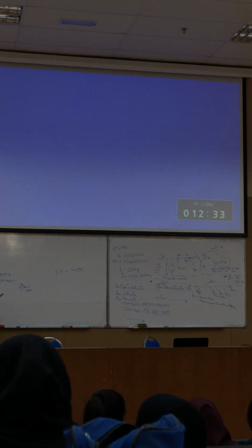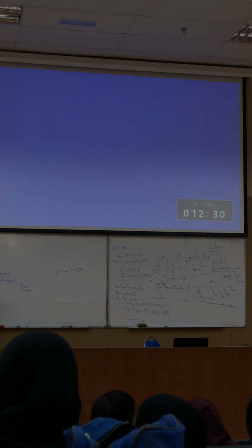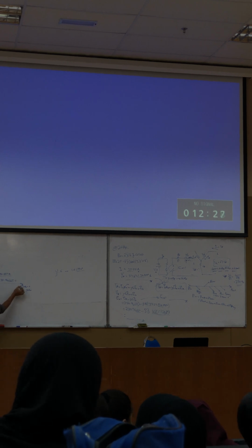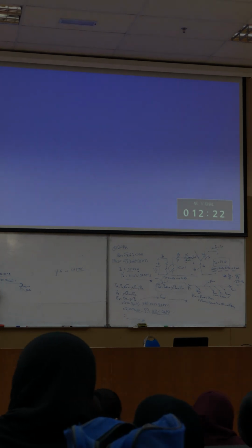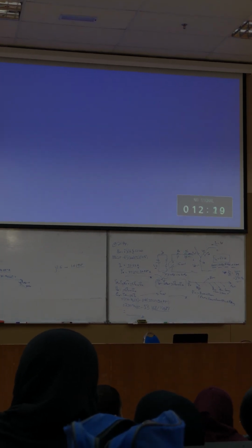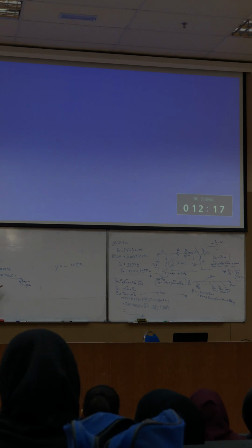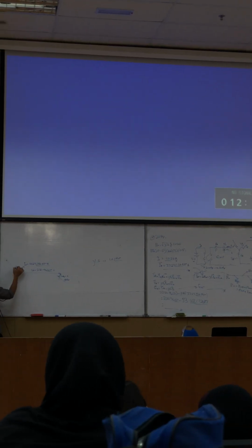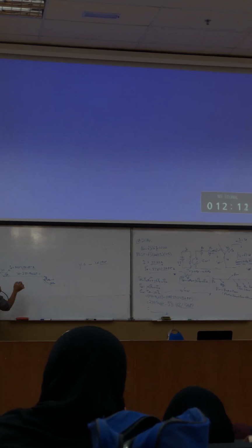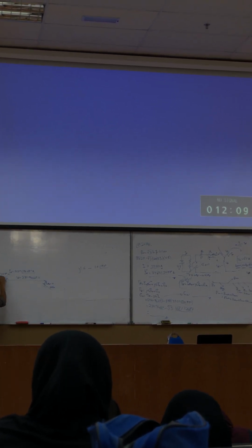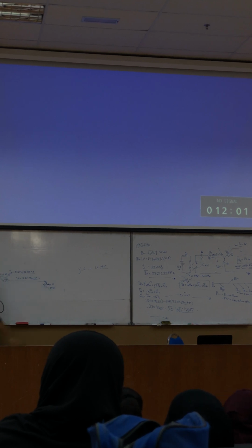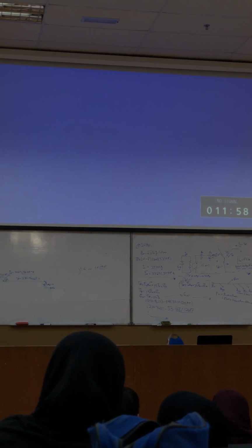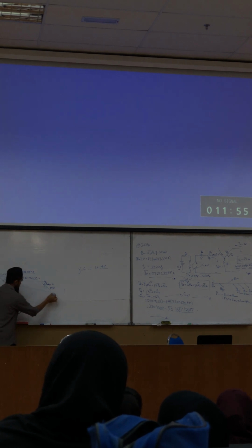So the angle is logical because you see the angle here, which is 90 degree of your current, and here, if you draw here, this is the angle of your jXS IA, which is 126.87. So the same angle. Angle for IA RA here. Angle for jXS IA is here. So it's logical. Fine. So your EA will be here.